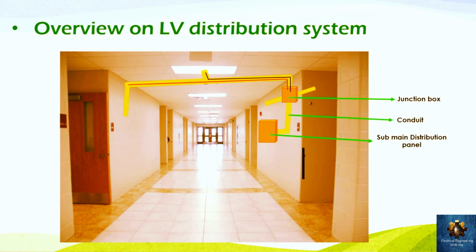And for the neutral wire, it's connected directly to the luminaire, while for the line, it will go to the switch firstly. This is for the controlling switch to turn on or turn off the luminaires, so we control the luminaires using this switch. Hence, the switch will cut the line, then the line will go back to the luminaire to feed it. And all the lamps will be connected in parallel through that way for the switch to control them. So that's about a general overview on the different components of the distribution system.